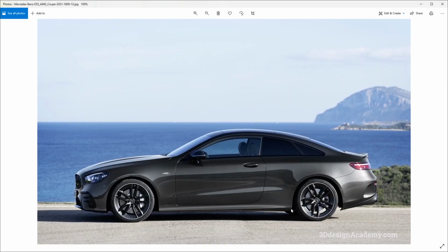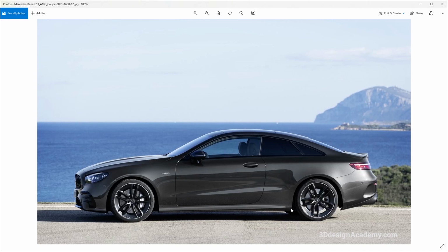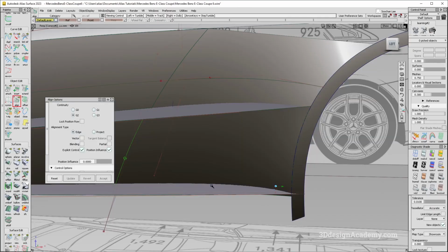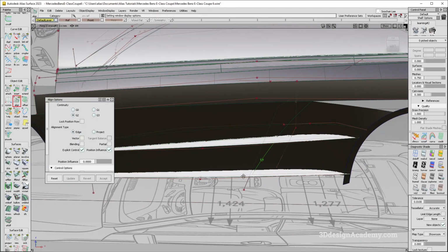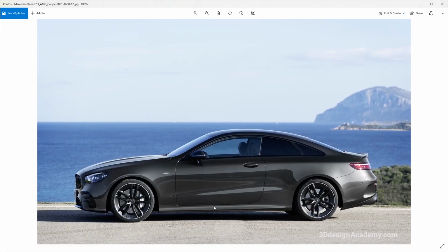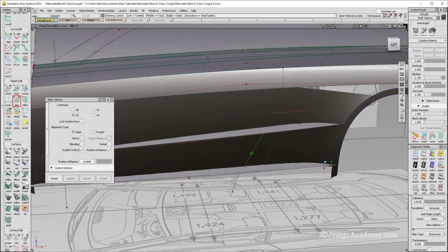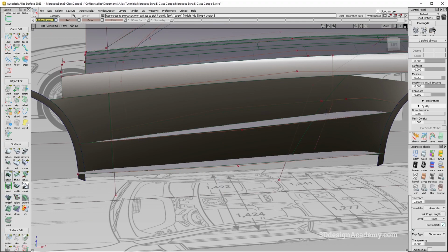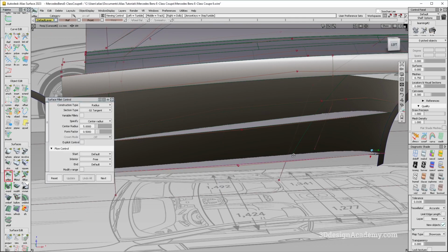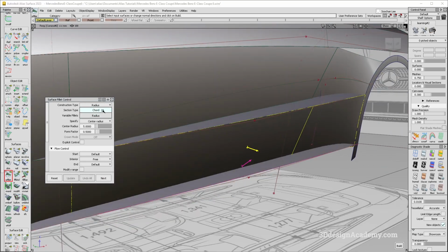hook towards the end. Now this probably needs a little bit of refinement also, and one thing though is right now this is just a hard edge. It doesn't have a proper highlight, so that probably needs to be done in the end. Actually, speaking of which, I'm going to see if I can just put a fillet here, or if I should do a freeform blend. We'll take a look.